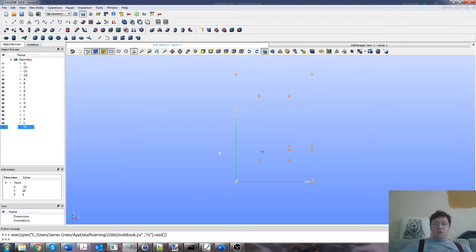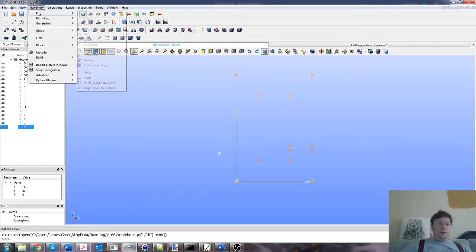There is a coil solver model in Elmer, and there is another model called circuits and dynamics, and we will use those eventually, or we'll use the circuits and dynamics model eventually. So I should be careful not to call it solver, and I should be careful not to call this a coil, because really all it is is a rectangular section in which we would impose a current density. It's not a coil, but we all know that this is an inductor and that's a coil. Or if you didn't know that, then you do now.